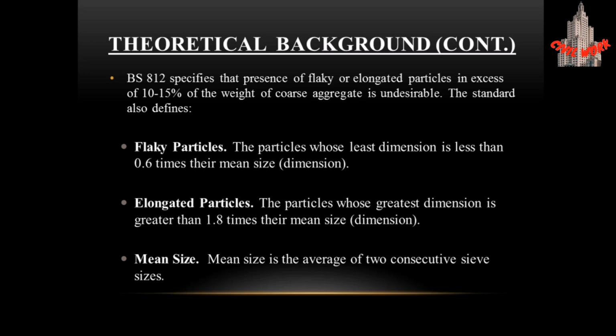The flaky particles are those whose least dimension is less than 0.6 times their mean size, and the elongated particles are those whose greatest dimension is greater than 1.8 times their mean size, which we have discussed earlier. Mean size is the average of two consecutive sieve sizes.